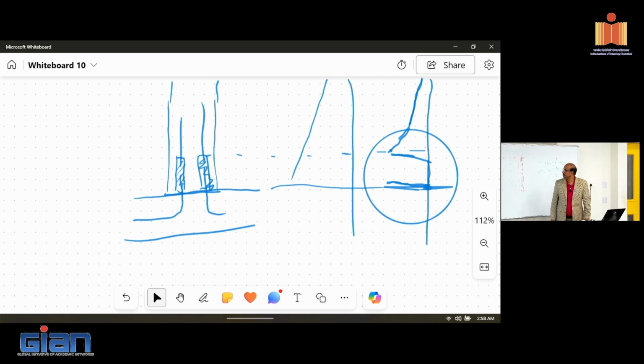This strain will not come all the way to zero, right? Because still you are mobile. Probably not, it's a smaller value is what I'm saying. So there's movement, so your strain demand, this is an inelastic strain, probably goes down like this, and then goes up, and then shoots up again, and gives a strain.